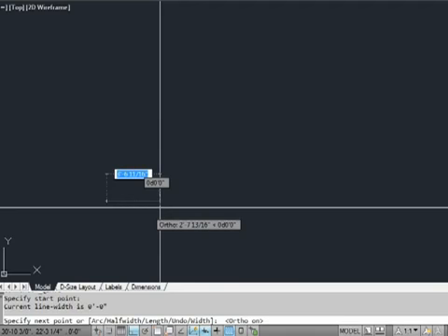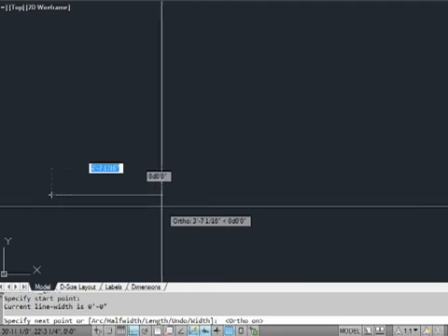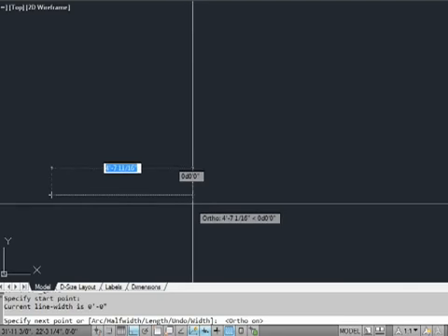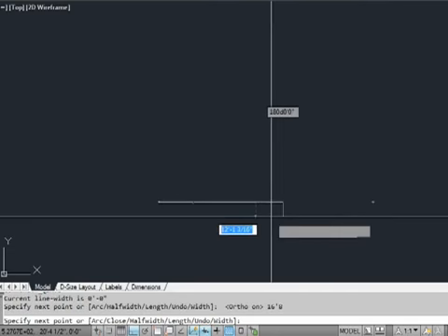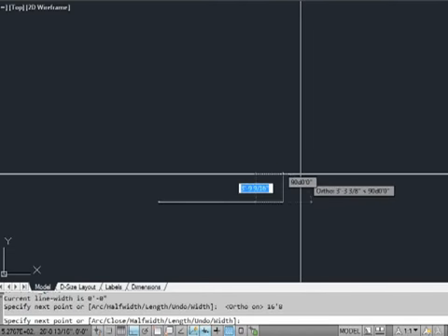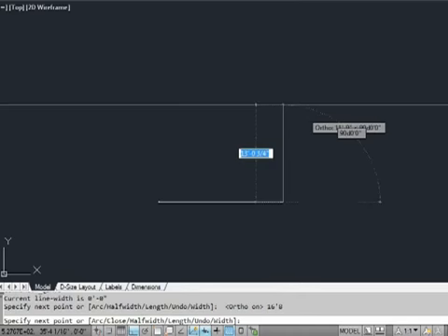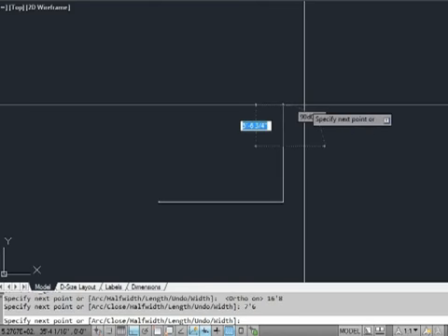So we're working in inches and we're just going to need to tell AutoCAD how far to make our walls. This part is going to be 16 feet, 8 inches. Press enter. Congratulations, you just started your first official drawing. Now we're going to draw up, or vertically, 7 feet, 6 inches. Type it in, press enter. Don't forget your feet designation with the apostrophe.